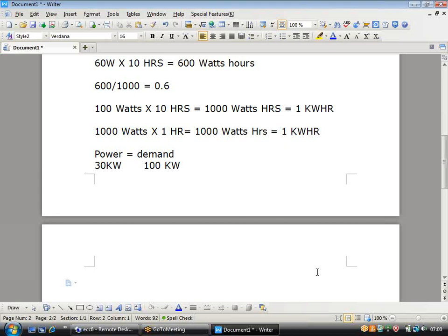Okay, that means next month when it starts reading, it's again going to record several readings in the power meter, and among the readings it has, it's going to show us one maximum instantaneous power that it is actually utilizing for a period of 15 minutes. Okay, so for an energy consumption meter, there's no resetting. It keeps on working in an aggregated way.